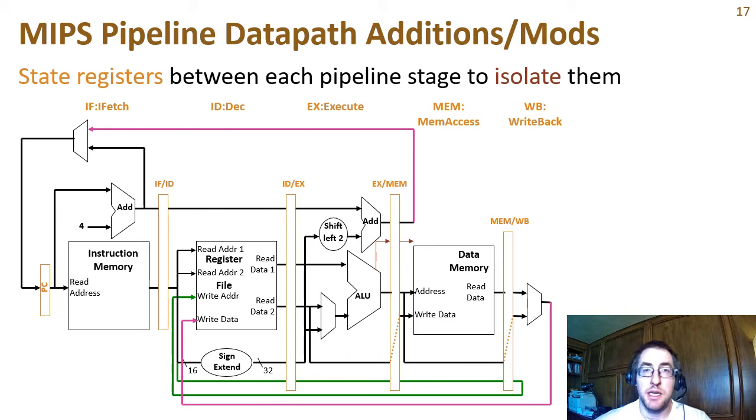They're registers. They update their value at the end of the clock cycle, so on the falling edge. And they latch the value of the output of the stage in order for it to be consumed by the next stage in the next cycle. This way, it doesn't matter how quickly any particular path through a stage goes. All paths end up being synchronized at these interstage buffers.